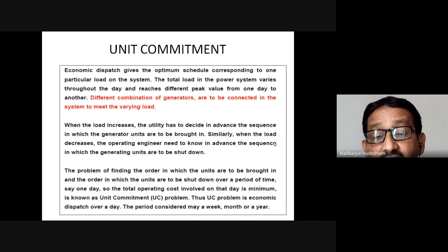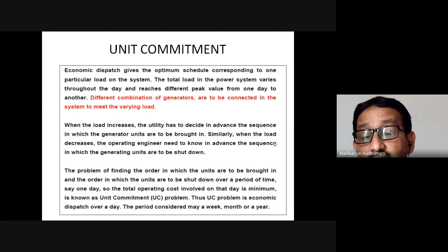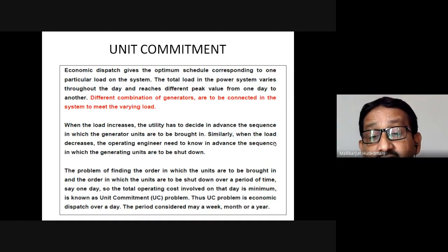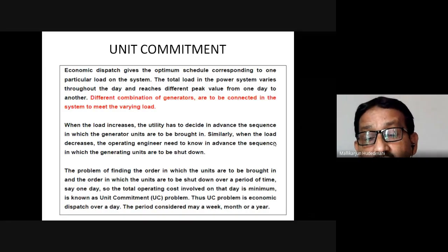A certain path has certain transmission sections between bus 1 and 2, 2 and 7, 9 and 11, and so on. Imagine a route of delivery for a certain megawatt. If that route finds a fault and one of the elements in between opens due to the fault, how do you meet the requirement of the load without affecting reliability? An alternative path must be chosen. There must be a security concern taken into account if this section fails.